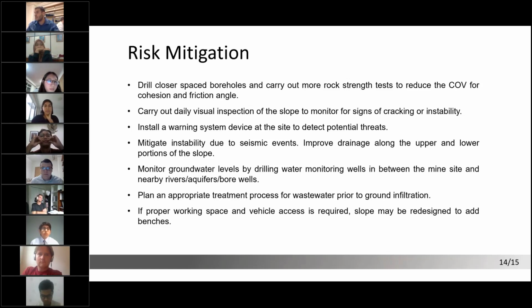Yeah, I guess if it was in an area where you would be expecting seismic events, it would be important to do some sort of test that would test how the rock would move down the boreholes. If it's mostly rock, we would be just taking rock samples. You could take the rock out and then test the strength while it's out of the ground. But doing in situ tests would be important too.